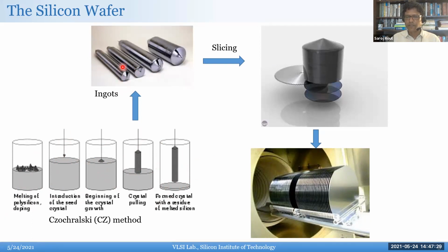You can see there are different sizes. I think this probably is the 8-inch, 6-inch, and then maybe 4 and 3. And I would say the length is probably about 3 foot, and this one may be about 4 foot. So you get this large solid bar, which they call an ingot. And then they slice it. Typically these are sliced to 5 to 10 millimeters sometimes, and after you fabricate it, they can grind it down to like 500 micrometers.